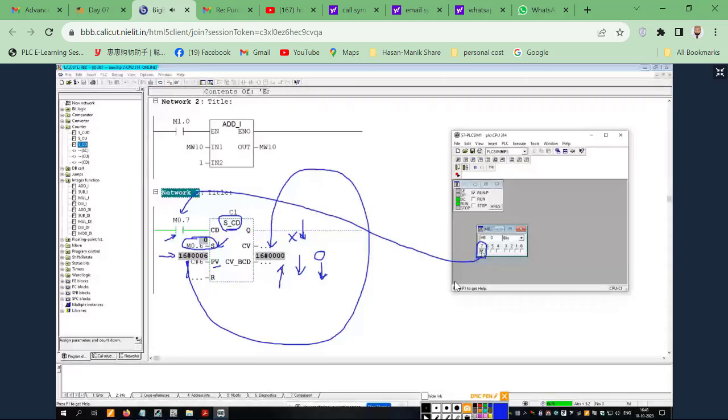Then you see 3, 2, 1, and it reaches 0. Below 0 it will not go in the case of Siemens countdown. Okay. So in Siemens PLC, the countdown operation will go only up to 0 in the accumulator. Below 0 it will not go. Okay, some other PLC may work differently, so don't compare that PLC and this PLC. Right?